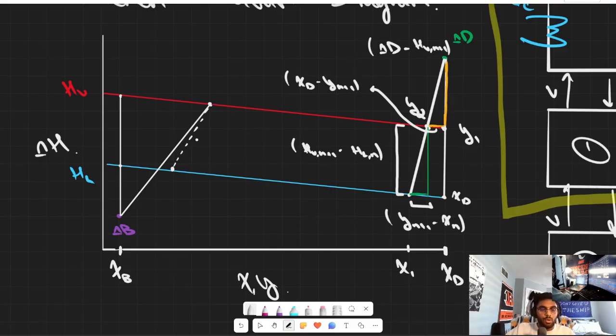And then this will go off and repeat the process. You will find another tie line down here. Maybe say it is in equilibrium with this liquid composition here, and this liquid composition will go off and give you the next vapor composition. So here is your vapor composition. It'll happen probably one more time here, and then that's your liquid composition for the bottoms.